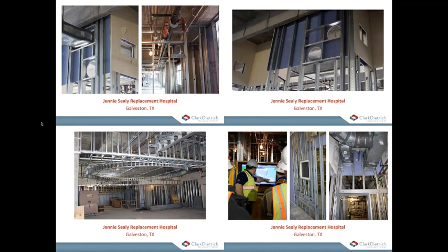Other ways it works out great is we're sometimes able to have the subcontractor be in the field up front. So up top left, you can see that the panelizer actually built this one right out here in the field. They pre-built everything right there in the field and left all the holes for the ductwork. So being able to leave the ductwork holes and walk off to the next layer or maybe the next second floor or so, and then have the other trades come in after you is a huge thing to have for our contractors. So if we can have the models right, we know exactly where the ductwork is going to be. We collaborate with the ductwork systems.